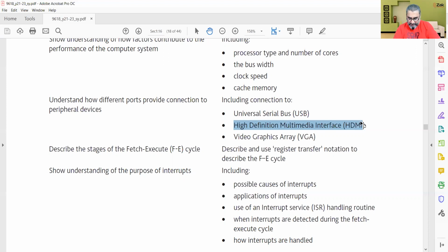So HDMI increases the bandwidth, meaning the amount of data in a unit of time, making it possible to supply the necessary data for high quality sound and visual effects. HDMI can also afford some protection against piracy since it uses high bandwidth digital copy protection. So HDMI is also preferred by a few of the vendors. High bandwidth digital copy protection, or HDCP, uses a type of authentication protocol.